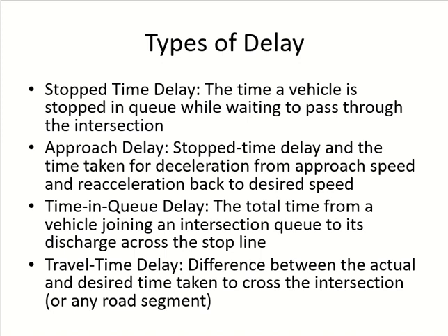Time in queue delay could be higher. Your stop delay could be 0, but you may still be in the queue. You joined, and when you came, the signal became green, so you actually didn't have to stop. But there were vehicles 5 meters in front of you, so you are in the queue. So you may have 0 stopping, but still time in queue delay. So time in queue delay could be higher.